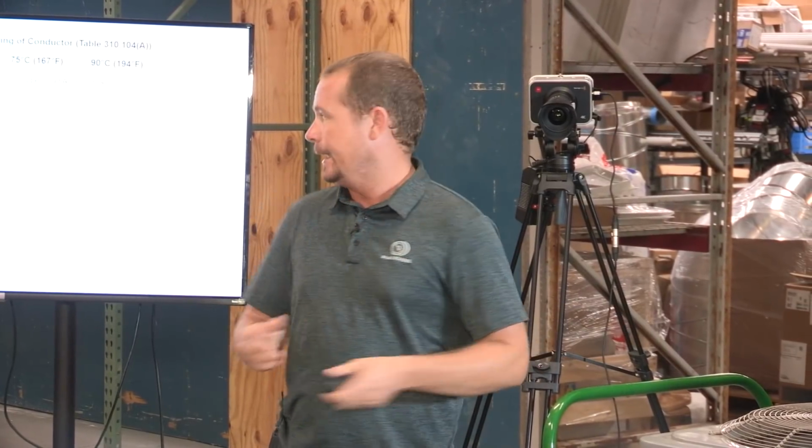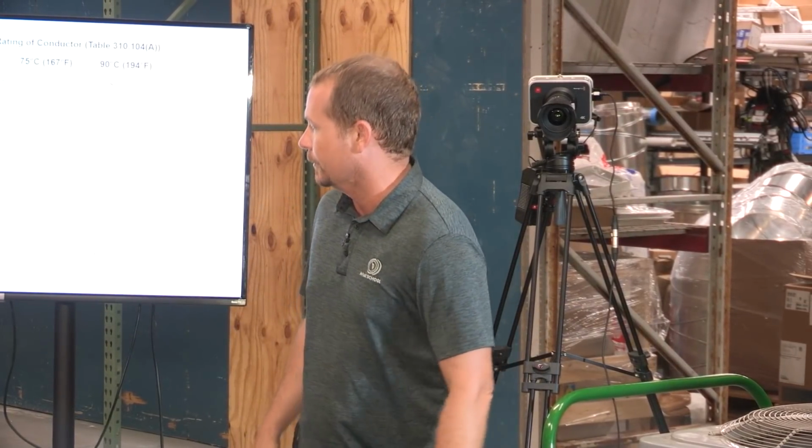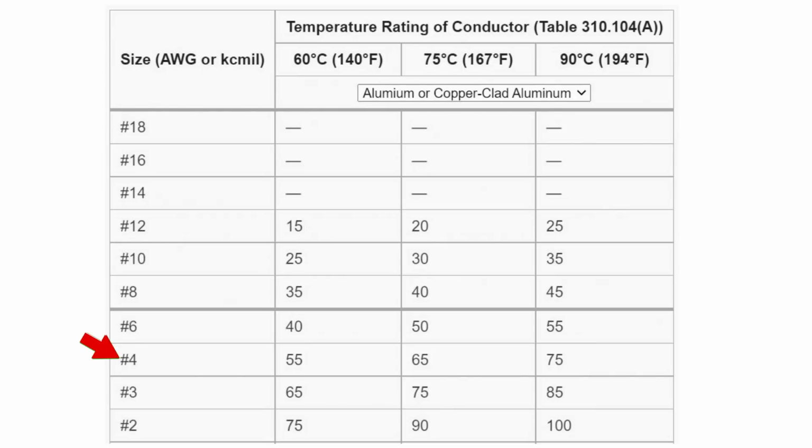Guys will see, all right, I got a sub-panel that's being fed by a 60 amp breaker, and we'll say it's copper. It's got number 4 copper wire going in between it. But then you go into the sub-panel, and it's got a 60 and a 30 in that. Well, that can't be right, because you got a 60 feeding a 60 and a 30. So long as that conductor is right, then it's fine, because that breaker is protecting that conductor.